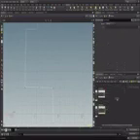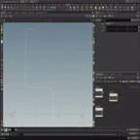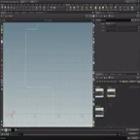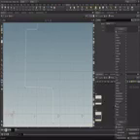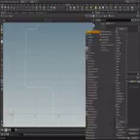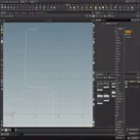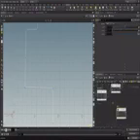First, place down a distance, and what we're going to check is the distance between the difference in the X value and the difference in the Z value. And depending on which one is larger, we're gonna set a switch. So let's compare these two. And right now, set it to less than. All right. So this is our basic switch value. After this, we're gonna mix some values. So this is basically a lerp.